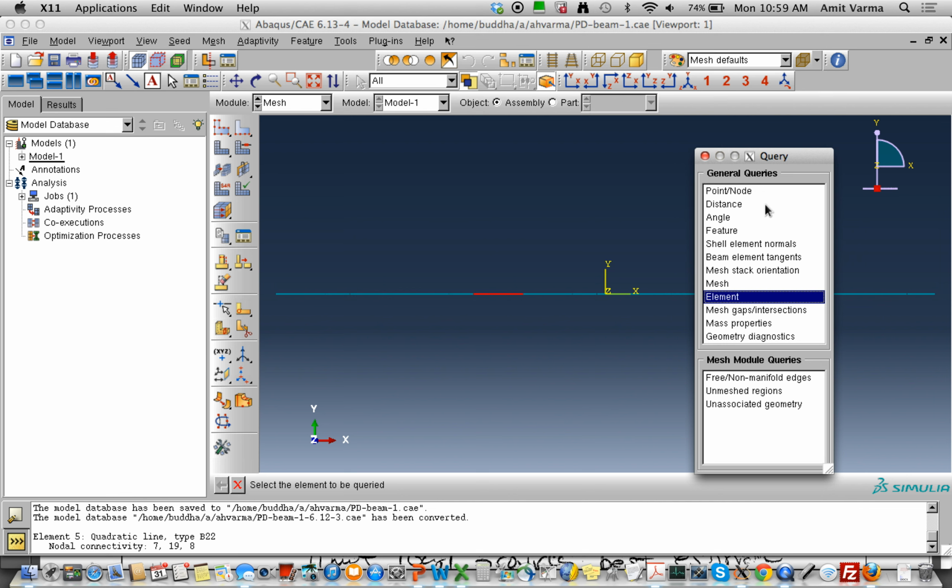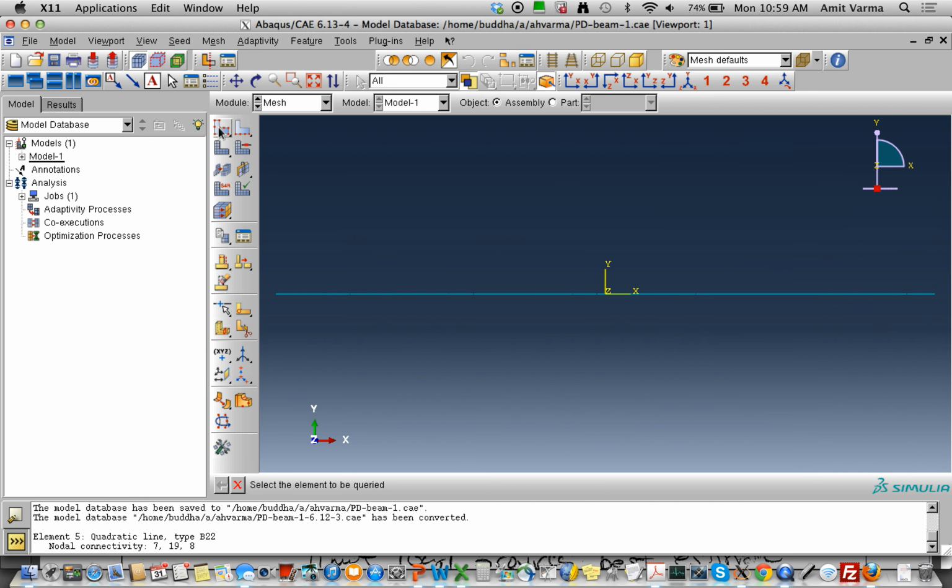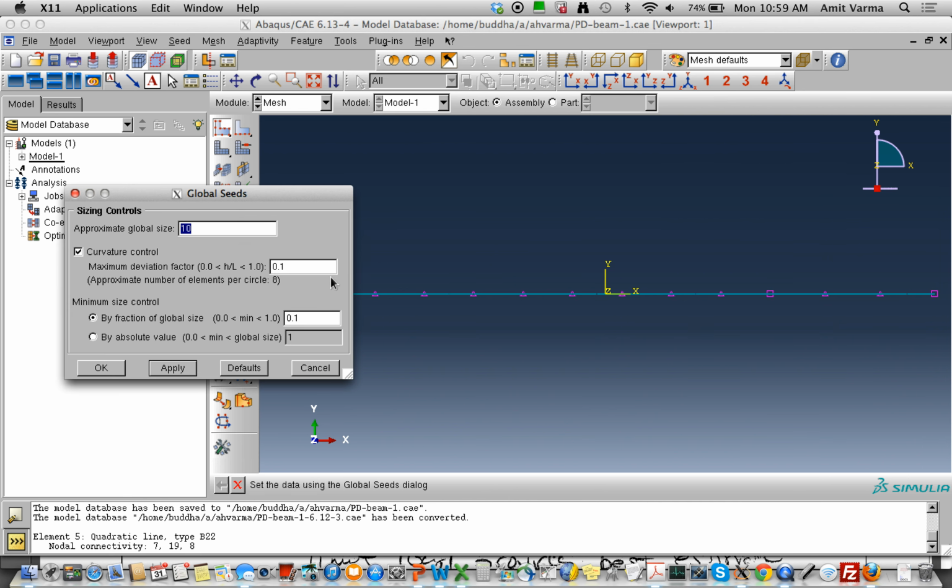Let's see what it is. I divided, it was a 100-inch element, you remember that? 100-inch beam. I broke it up into 10 pieces, so I have 10-inch segments. Now, did I have to do 10 inches, or could I have gone with 20, or could I have gone with 75-inch segments? I potentially could have tried a much coarser mesh. In this case, I didn't need to.